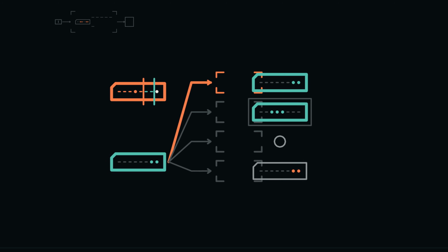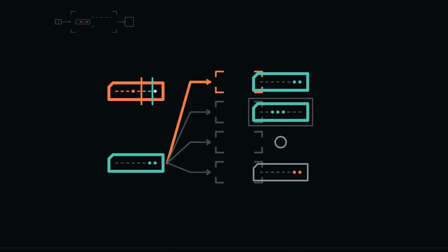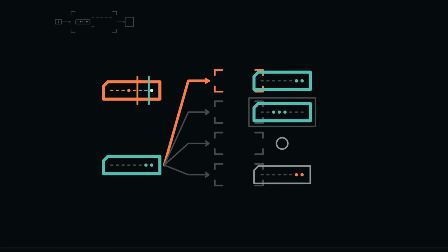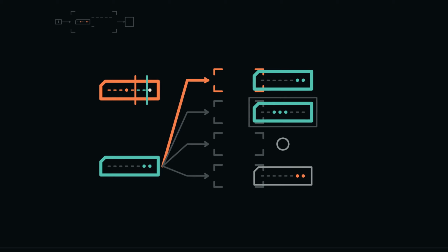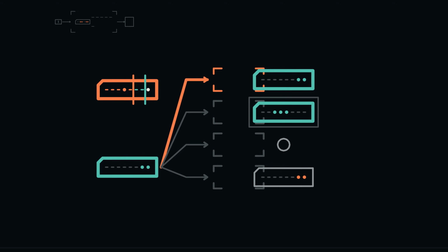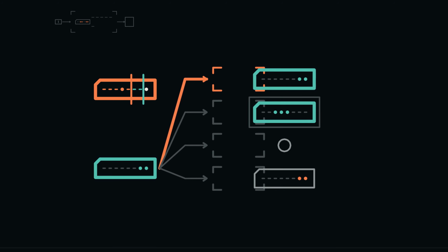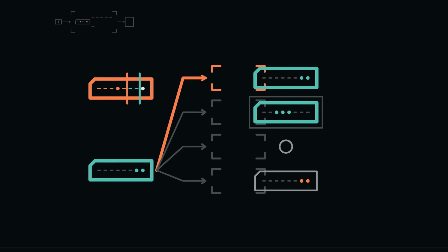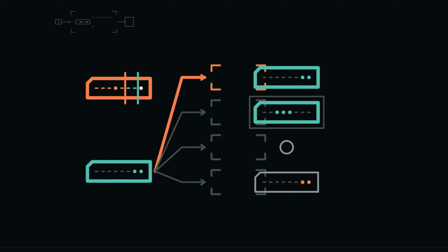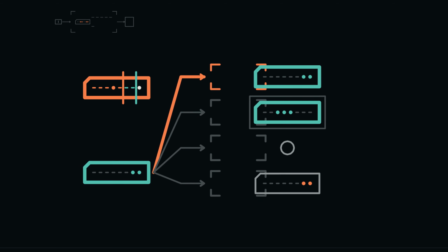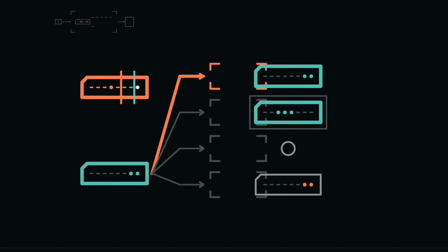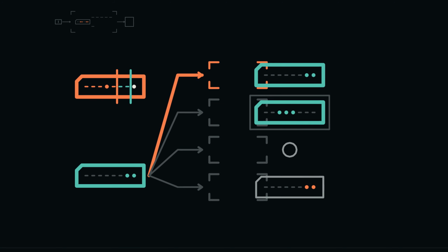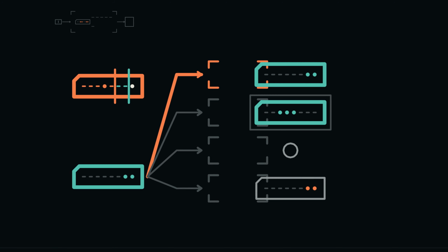Decode hexadecimal 11 followed by 03. Byte 0, 00010001, separates into opcode 00010, A equal to 00, and I equal to 1. Opcode 2 is the load family. A selects R0. I equal to 1 says B is an immediate value rather than a memory address. Byte 1 is hexadecimal 03. The complete instruction is load immediate R0, 03, and its promised transition is R0 receives 3. The flags are preserved. No memory read of address 3 occurs because the immediate field supplies the value directly.